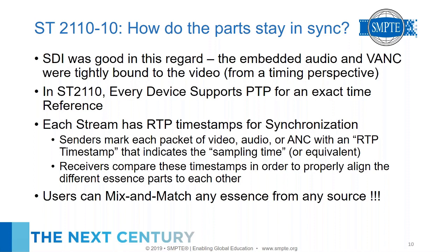Yeah. If you had say a SCTE 104 or a SCTE 35 trigger, normally that would be carried as a SCTE 104 message in VANC, and so similarly in 2110 it would be carried as a SCTE 104 VANC message wrapped in 2110-40.